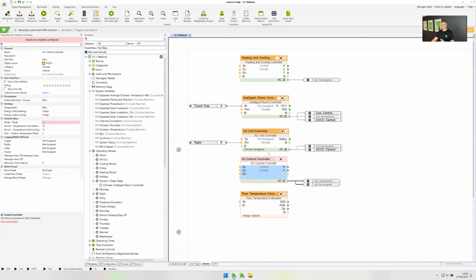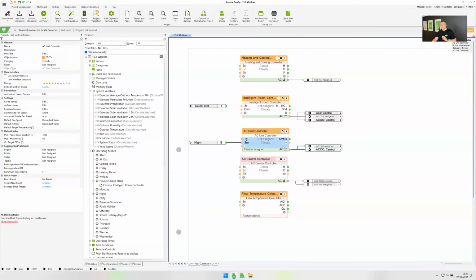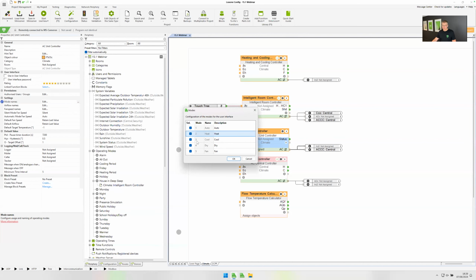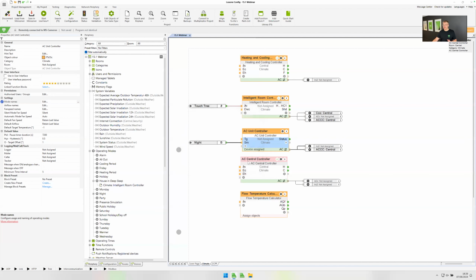So how would you configure the inputs and outputs of the AC unit controller when using other interfaces like Intesis or Core Master Net? So the AC unit controller is primarily designed for use with the AC controller. It can be used with third parties like Intesis or Core Master, but it will require some additional outputs. The reason being is if we look at the different IDs and the different names of the outputs, we can change the description to what the customer understands, but the physical functionality behind it can't be changed. So to be able to replicate that same behavior, you would need status blocks, etc.